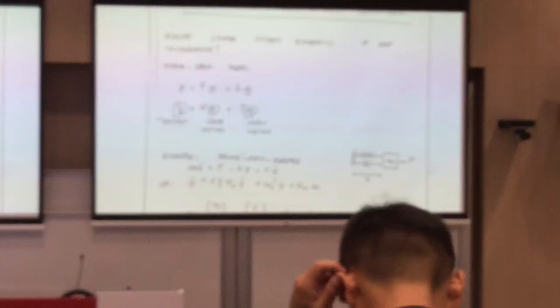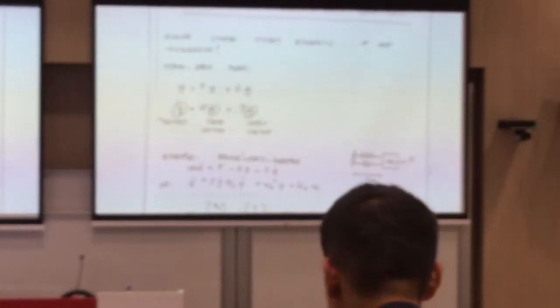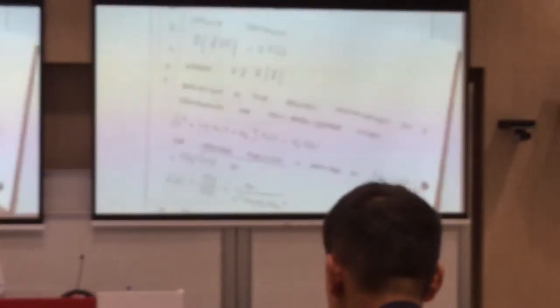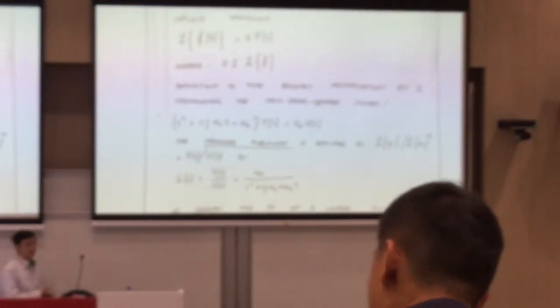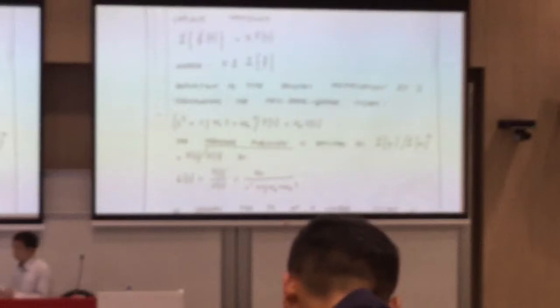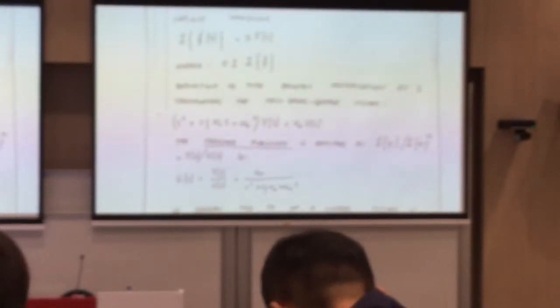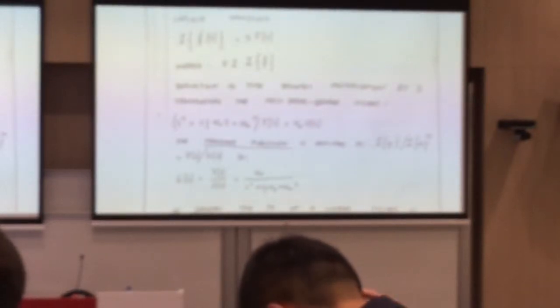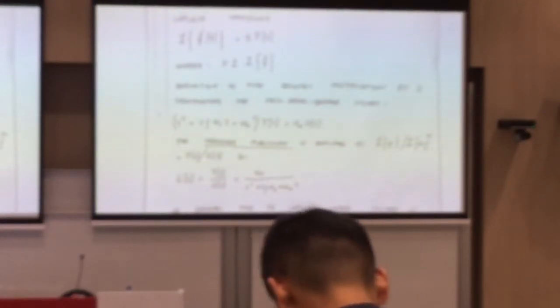Classic control, what does it mean? They use some mathematical tool, which is called Laplace. So you see this one, they use the Laplace transform. Basically, the Laplace transform transforms your differential equations into polynomial functions. For example, if you have a second order differential equation, then you convert to a second order polynomial function. Then it will be much easier for you to solve the polynomial function rather than the differential equation. This is something called the classic control.